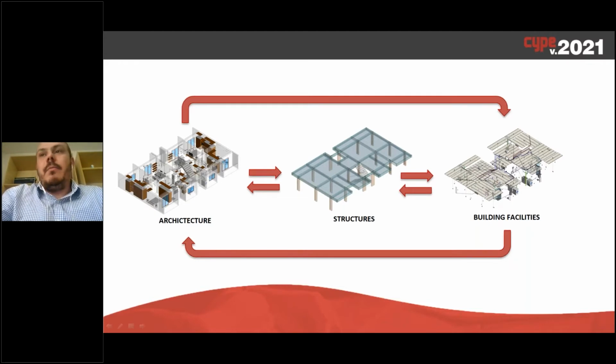In the case of the BIMserver.center platform, we will have different IFC files: one for the structural model, one for the HVAC system, another for the plumbing facilities, another for electrical facilities, and so on. Today we will explain how a BIM manager or a BIM coordinator can coordinate this situation and look for clashes or incompatibilities between these IFC files.